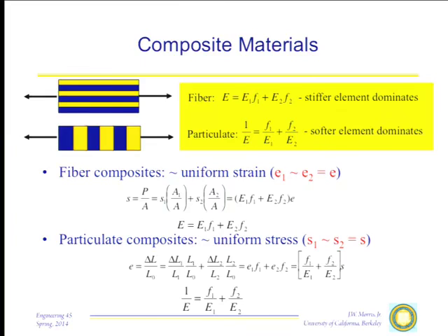Well, really what's happening is, if I pull on this composite, the criterion is the strain in the fiber is the same as the strain in the matrix. And if I just use that, I come to the conclusion that the effective modulus of the composite is the average of the moduli of the two pieces. So if I have something like a graphite or even glass where I have a very, very high modulus in the fiber, I can make a unidirectional fiber composite that has a very high modulus because of this law of averages, and one of these numbers being very large. And for things that can use this high modulus, like shafts or golf clubs and so on, this can be a very, very useful configuration. But it has a problem. I'm only getting this modulus in one direction. If I consider what happens if I start trying to load this in other directions, suddenly my modulus goes away.